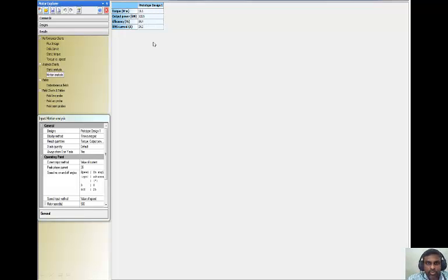If I do that and get the results, you can see the torque I want is 10 Newton meter, and we get 10.1 Newton meter, so it is satisfied. The output power is 0.526 kilowatt, and I want 525 watts, so that is also achieved. Efficiency is nearby 85%, and the RMS current is calculated based on the 35 amps for this particular speed, which the machine requires to produce the torque of 10 Newton meter.